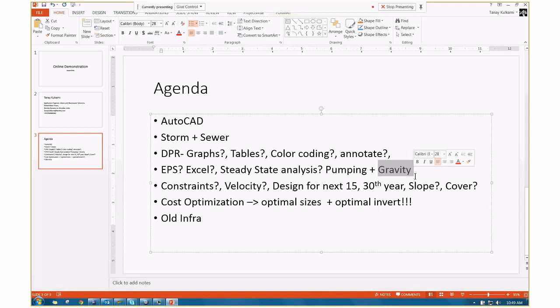That also means you are interested in knowing how much time it takes to fill the wet well, where all the water is being collected. So what is the time after which I should start my pump? For how many hours should I pump water or gray water from that wet well to another manhole on the upstream side, so as to optimize my pumping or energy cost? Yes, you're right.